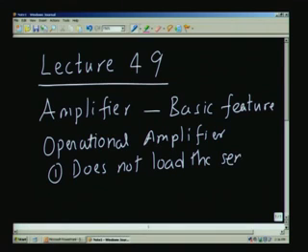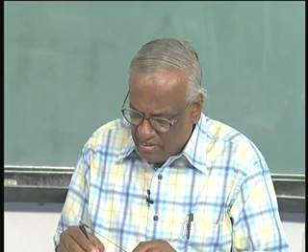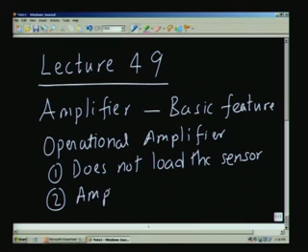So, it draws no power from the sensor or very little power from the sensor, amplifies the signal using external power. This is very important.